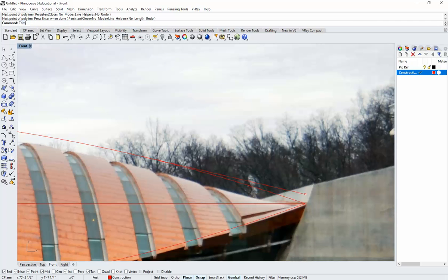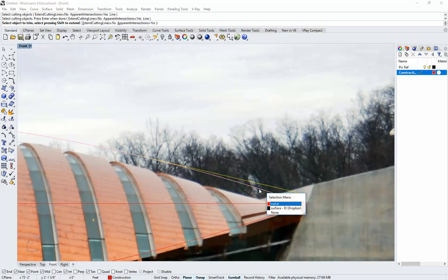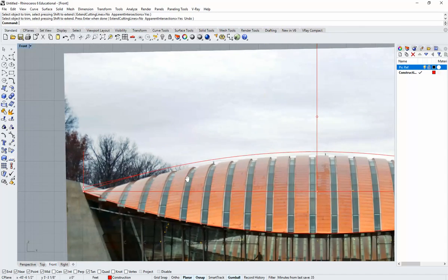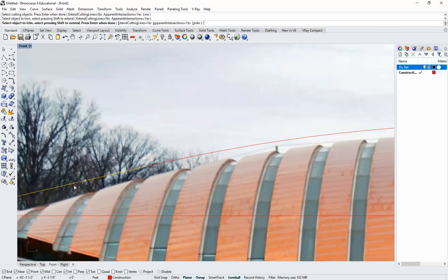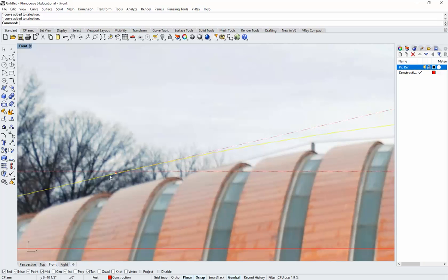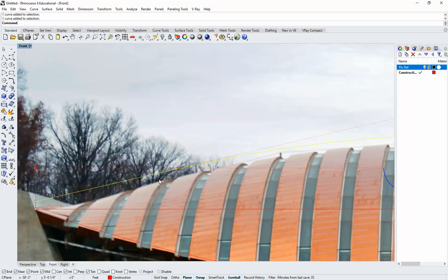These lines I just drew I can use to trim the curve. So I'm going to grab that. The other thing you're probably going to want to do is lock your picture reference layer because it keeps selecting on me. So let's trim like this. And because this line is tangential to that curve, it's a smooth continuation. There won't be any weird lumpiness in here. It's a perfect tangent from the shape of that curve relative to that point.